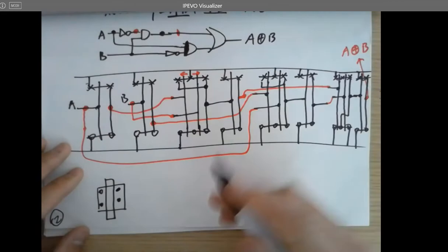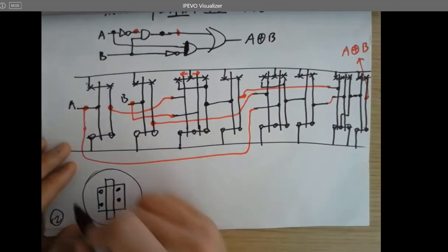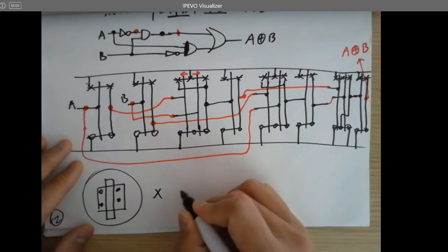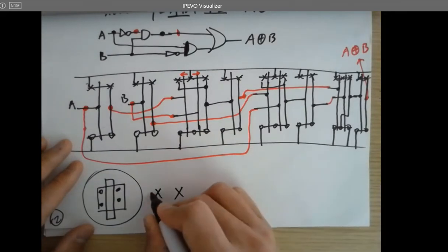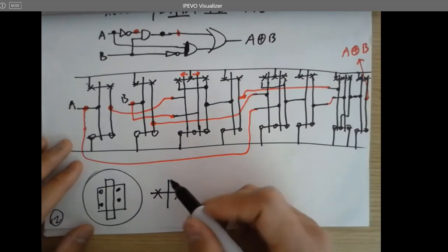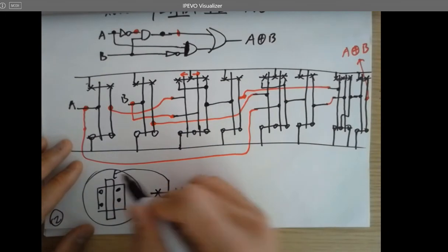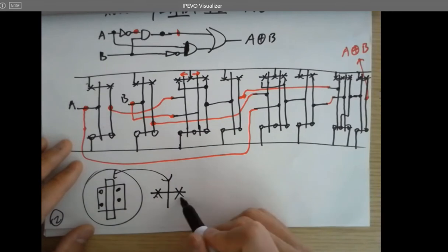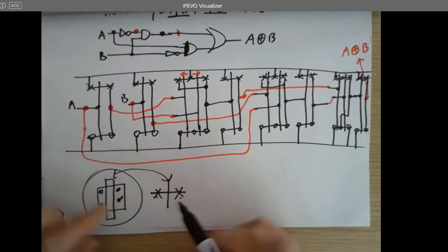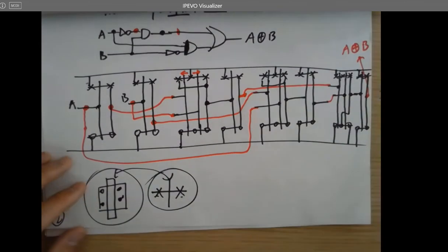So this is NMOS in the library in your Electric VLSI tool. And what we do, we just use two crosses like this and one stick in the middle. So this is a gate, which is the same as a gate in the middle. And these two are the two connections here, Vs and N plus. Right, so this is one NMOS.